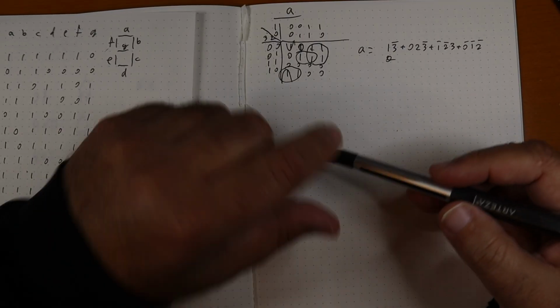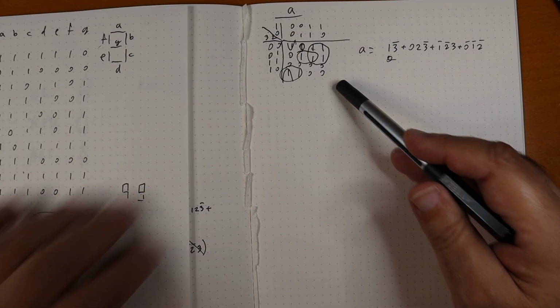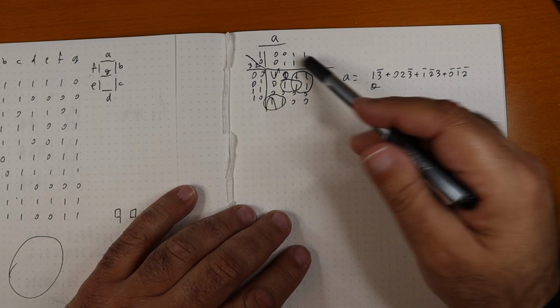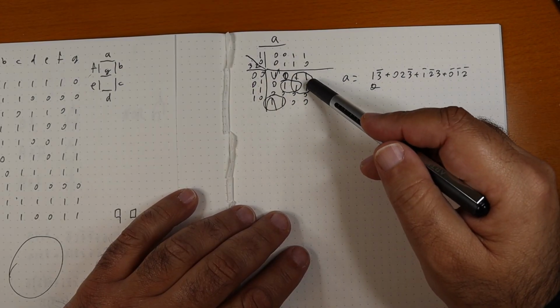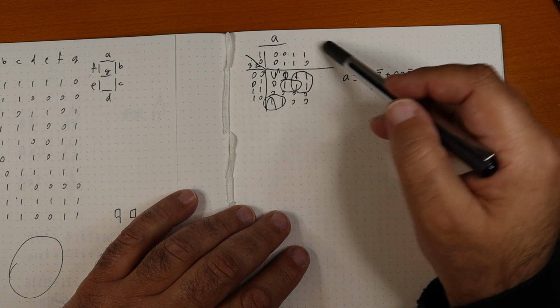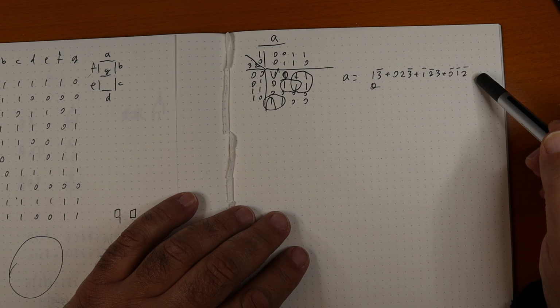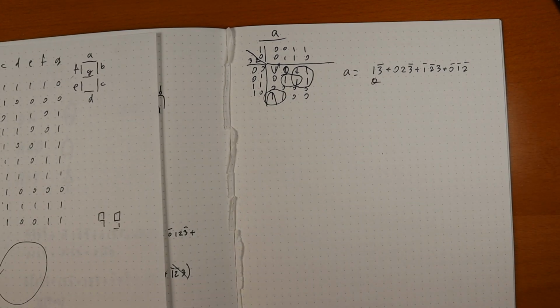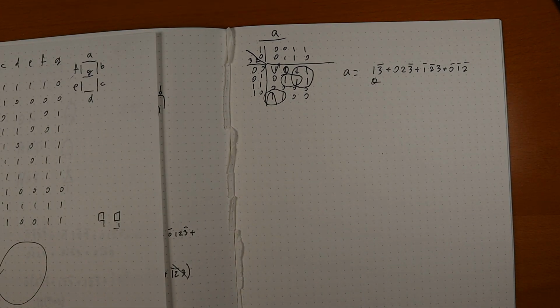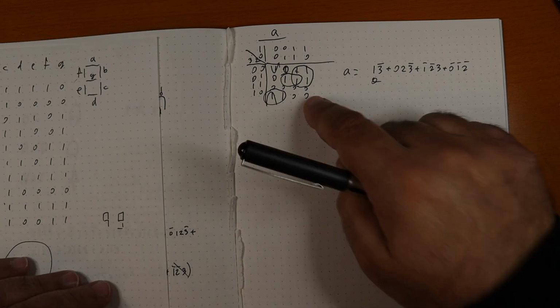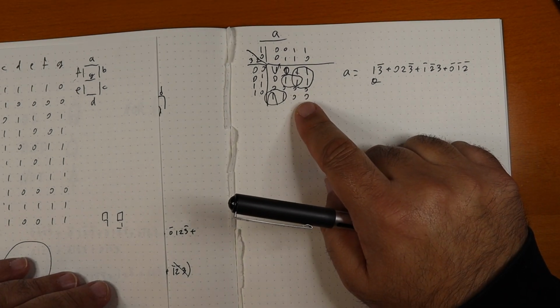So if we look at the Karnaugh map we did, the bigger the area I was using, the more inputs could be either 1 or 0 and wouldn't appear in the expression. So the bigger the rectangle, the better. But otherwise, I needed to cover all the ones in the design.